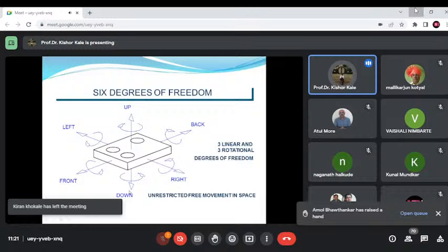So generally, scanners with laser rays are used as 3D scanners for data acquisition. Data acquisition here means we are taking various points. We are capturing the shape and size of the product which is to be measured or verified for the tolerances. First, we'll look at the coordinate measuring machine, a contact type of data acquisition technique. Second, we'll look at the non-contact type of data acquisition techniques.